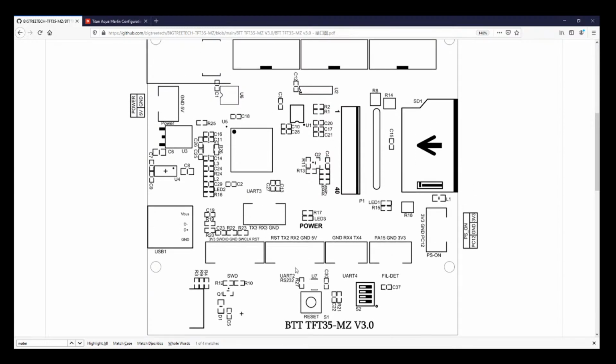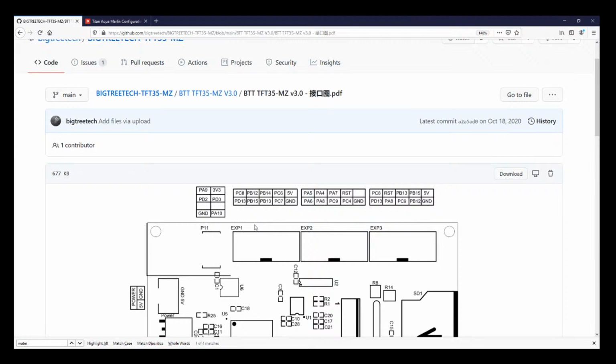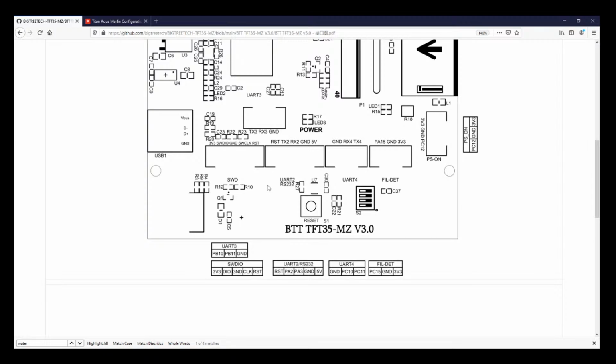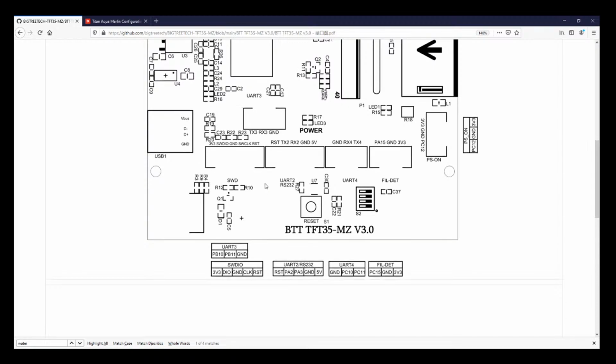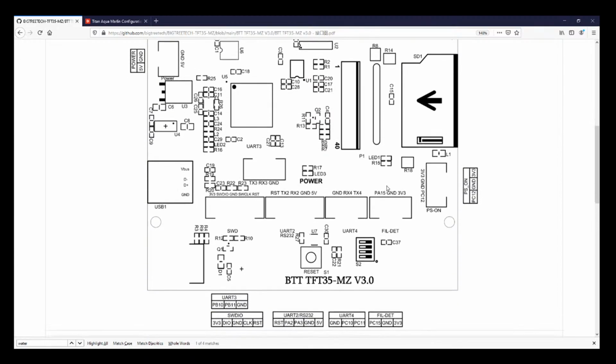Looks like there's 3 UARTs on here. So here, here, and here. And UART's just a wiring scheme that you can run with a certain chip to communicate with certain things. Just like SPI. SPI, they usually use chip select, which is a numbering system like mailboxes for different components. In this case, pins. But there's not very much more on this.